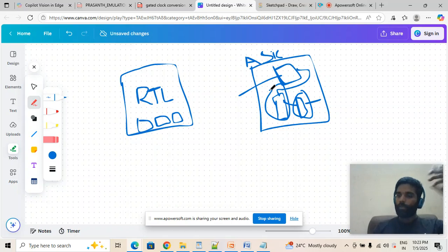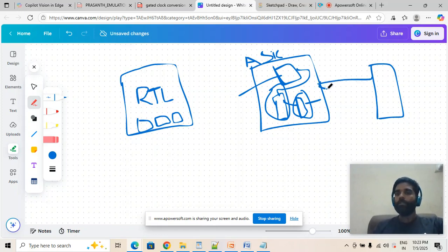So you write the code and you can start doing verification. This is my testbench that I write, and I start doing the simulation here. So this is my ASIC DUT, and this is my testbench. Can you use SystemVerilog or Verilog? It's always recommended to use SystemVerilog for the testbench, and you can use Verilog for the design. It's a very common practice. Verilog is used widely, so you can use Verilog itself for your design.